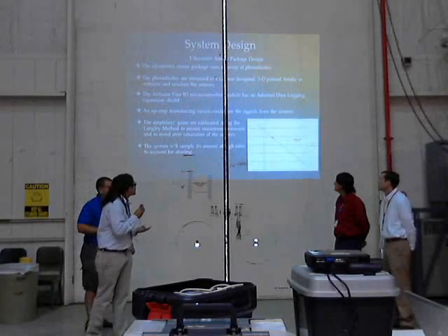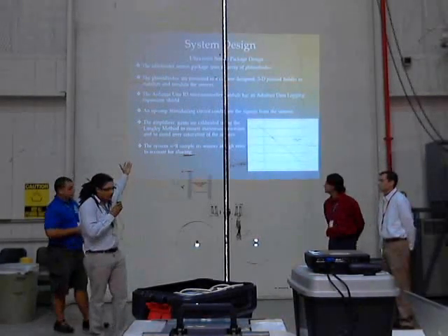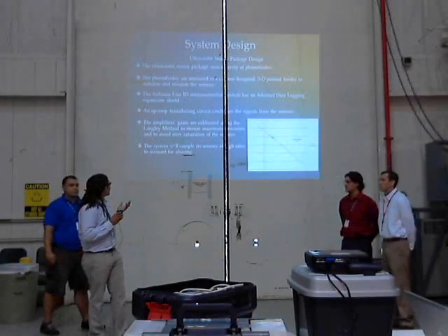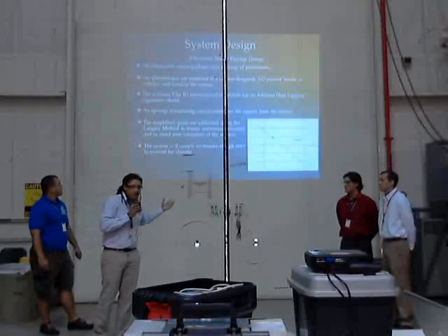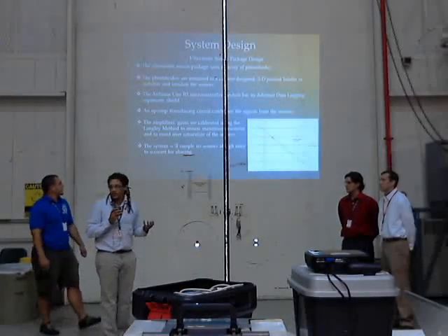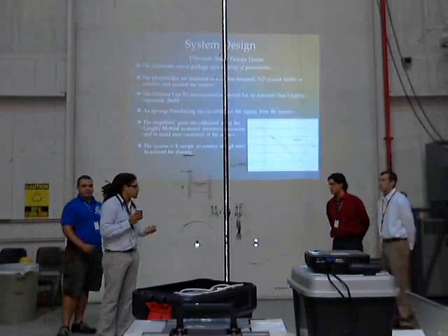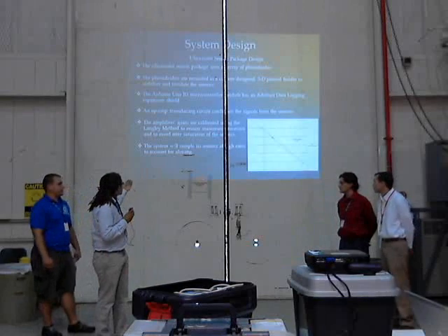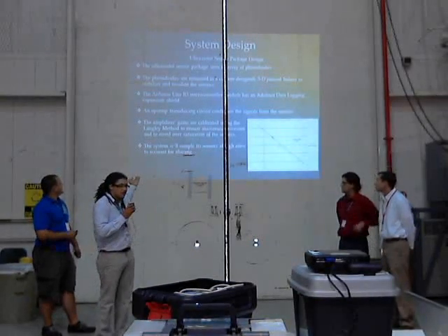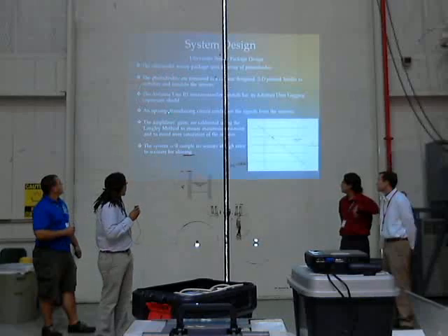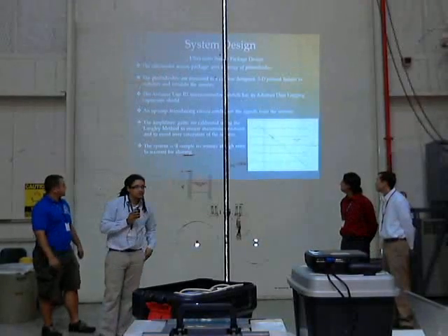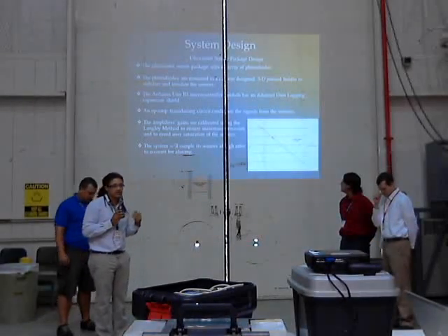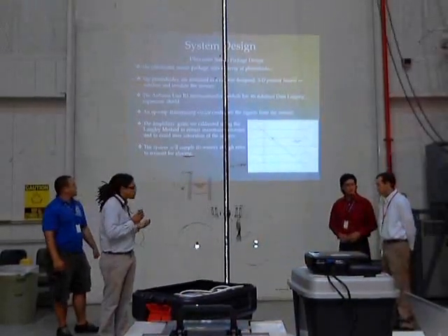The system design, we basically used an ultraviolet sensor package, one for each corresponding band. These diodes were mounted in a custom-built 3D printed holder, which we have some to pass around later. We use the Arduino controller as our main brain, and op-amp circuits to convert the current from the sensors to voltage, and also to control our gain.